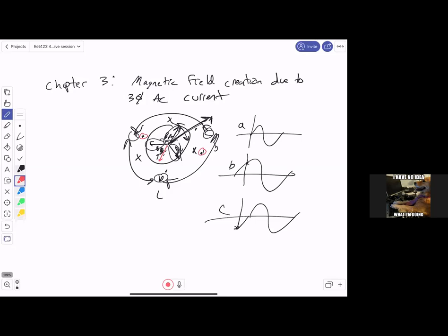So the whole thing to do these types of problems is to just draw your base values for where positive current is going to give me a magnetic field. And then I just plug in the values that I get here at one time. And then I just add those up vectorially. So literally I add my B sub A, which is going to be at an angle, plus B sub B, which is going to be at an angle, plus B sub C, which is going to be at an angle. I add those vectorially, and then I get a number. And then I rotate 30 degrees, 90 degrees, whatever you want. And then I'm going to go to time 2. I'm just going to continue to add those.